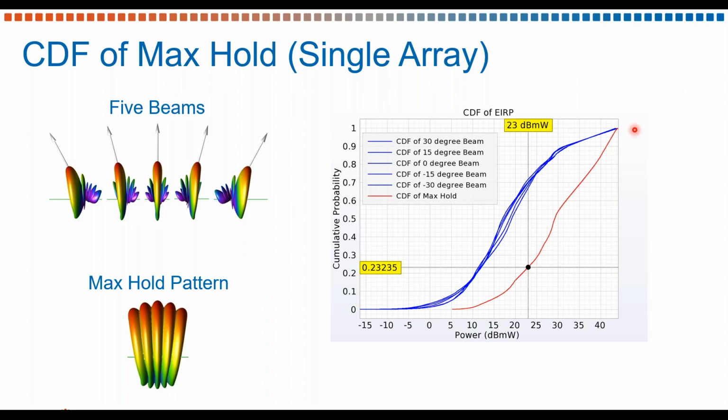Here you can see that each of these patterns have a maximum EIRP around 43 dBm. And if, suppose, we have input power of 23 dBm applied to these patterns, roughly we have 30% of the pattern which is directed, and it also shows that it's not doing that good of a job when compared to covering a much larger area.